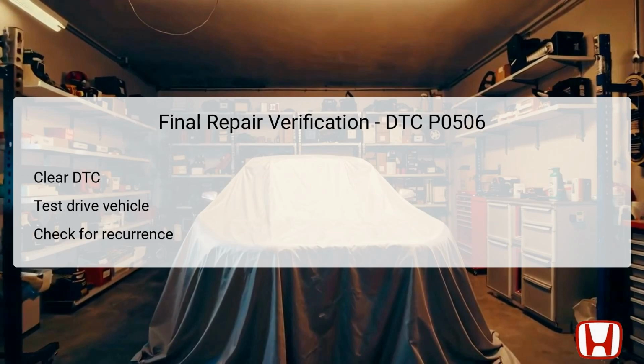Once repairs have been conducted, it is vital to perform a final verification of the issue related to DTC P0506. Start by clearing the DTC from the PCM using a scan tool. Following this, take the vehicle for a test drive under various conditions, including different speeds and gear shifts, to evaluate engine performance comprehensively. Keep an eye on the dashboard for the check engine light. If it remains off and no pending DTCs appear after the drive cycle, it typically indicates a successful repair. It's crucial to ensure the RPMs sustain their stability throughout various driving scenarios to confirm that the idle control system is functioning as it should.